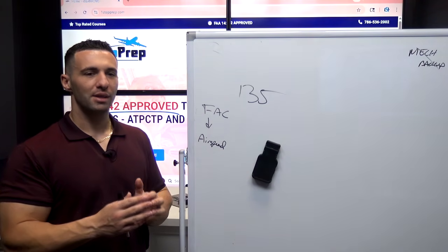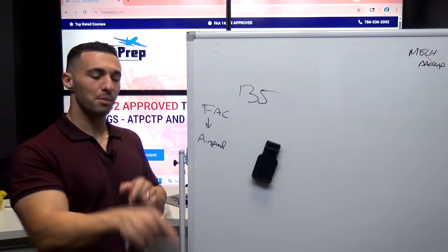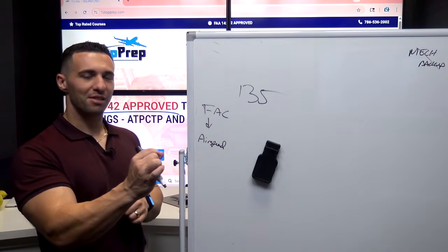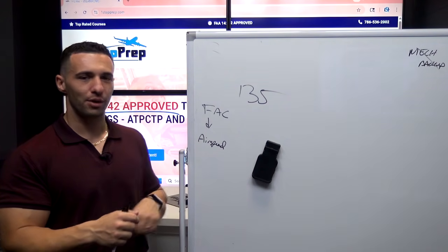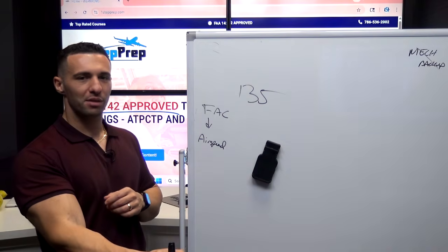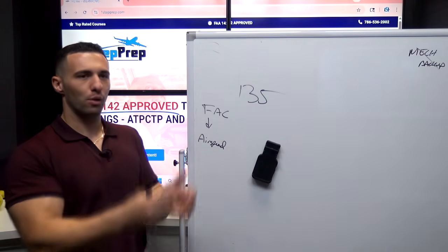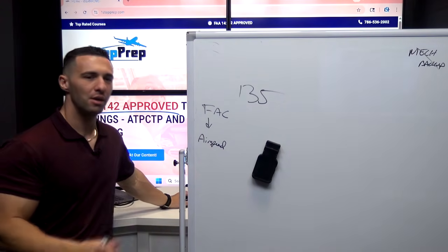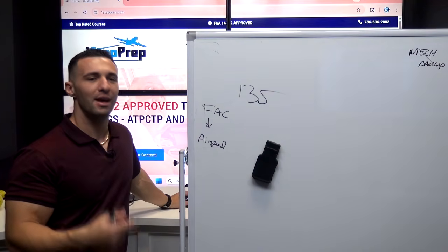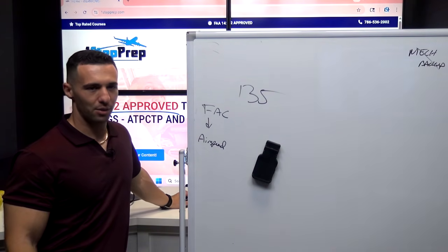So the VLS on the airspeed tape is variable with configuration and G-loading as far as what the airplane's feeling. That's not true for the VLS in the MCDU. If you look at the VLS in the MCDU, that number's fixed. Even as I'm moving the side stick, throwing flaps out and moving the spoiler, that number just stays there in that one calculated spot while the presentation is moving all up and down all over the place. So that's the difference: the one that's pictured is FAC generated and variable with configuration and G-load, and the one in the MCDU is not, it's fixed.